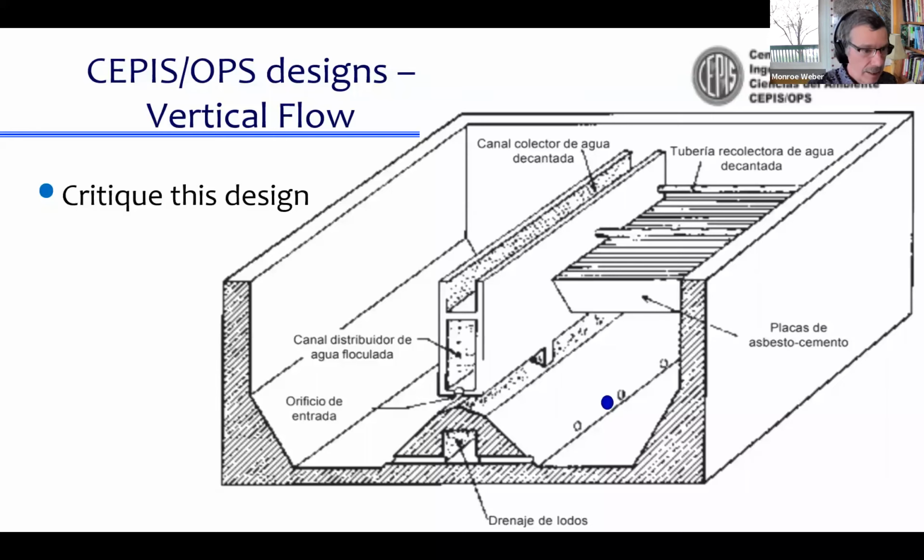Okay, so how does the sludge get out of the bottom? Do you see that? I didn't detail that, but there's these little holes. Like, here's a little hole, and that little hole is connected to this drain channel. So there's a valve at the end of that drain channel. Presumably they open up that valve and it starts sucking out of those ports. What do you think about the ability of those ports to empty the sludge that's sitting on the bottom of the sed tank?